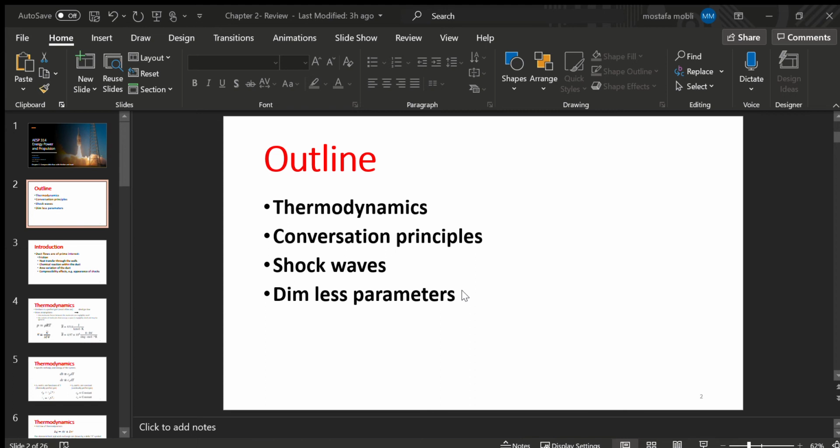And the momentum equation, which is a directional equation and relates force and momentum together, is essentially a force balance equation, if you will. And I said balance. It's the balance of forces within a control volume. The momentum equation tells you about whatever changes in momentum you have inside a control volume. Right? Do you guys know what a control volume is? Just assume you all know what a control volume is. Yes?